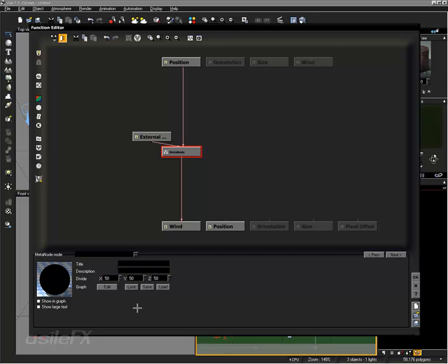Now in this case, it doesn't really affect the total output, and changing the internal unit shouldn't have that large of an impact. But if you were manually connecting a vector and typing in a number, rather than using another object to control it, you might have to type in a lower or higher value. Because if we were using an internal unit of 1, then the vector for 5 meters would be 5 and not 50. So if you're using the composer with manual number entries, that's just one thing to keep in mind about the vector.